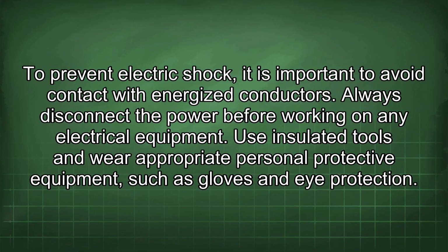To prevent electric shock, it is important to avoid contact with energized conductors. Always disconnect the power before working on any electrical equipment. Use insulated tools and wear appropriate personal protective equipment such as gloves and eye protection.